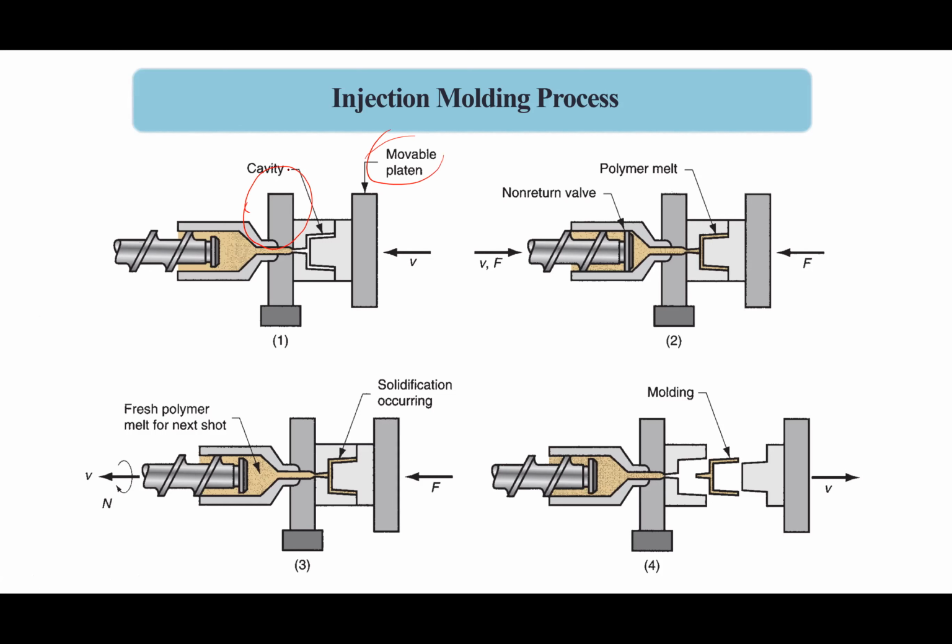There's a mold release agent. The name of that is the mold release agent. It is sprayed on the cavity so that the plastic product does not stick. So there will be a system which will spray the mold release agent at every cycle, right? A kind of, yes, of course. Okay, thank you, sir.